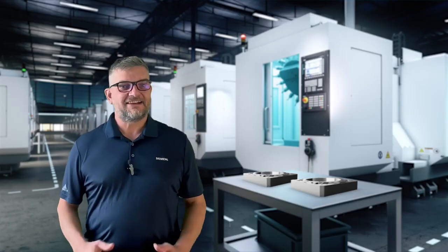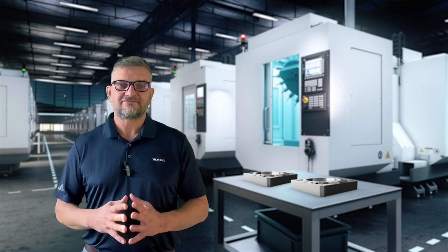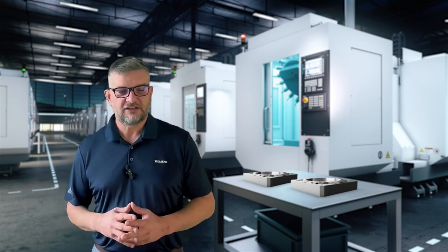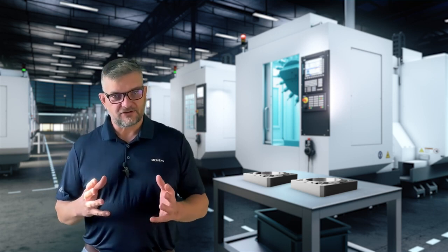Now that we've seen Ashish showcase the new quick roughing operation, an important addition to our 3-axis milling capabilities, it's time to shift our focus to the exciting world of 5-axis machining. Yet another new operation is called wall finish barrel swarf. As the name infers, it's a finishing operation, 5-axis, to be used with different types of barrel tools. And it's very good for cutting deep pockets or deep planar walls.